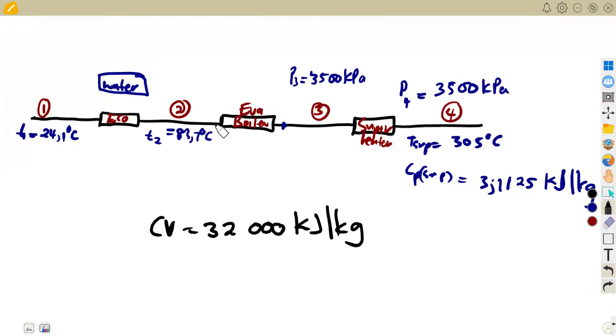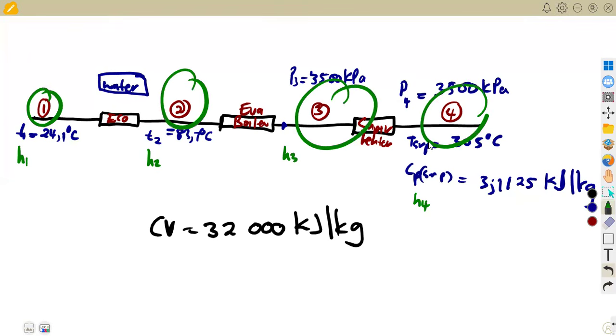And yes, it's going to enter the boiler now, where we are told, I think when we read, that the steam is wet. We're given the percentage of the wetness. It means this steam is wet, but it can be dry. When they tell you that it's dry, it means you are going to take this as your Hg. At this point, remember, we need the enthalpies. From point 1, we need H1, H2, H3, H4, at point 1, point 2, point 3, point 4.